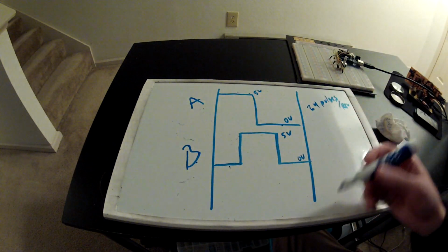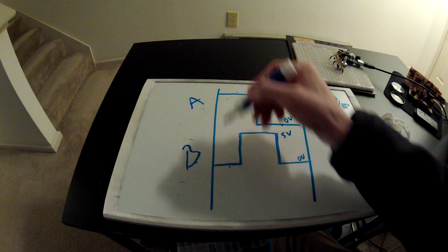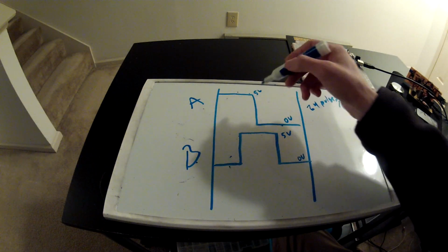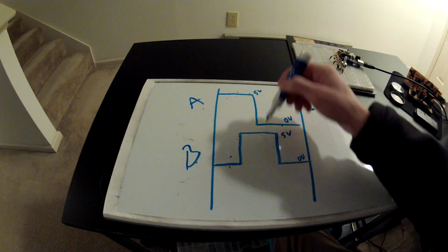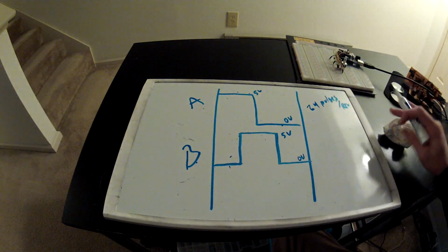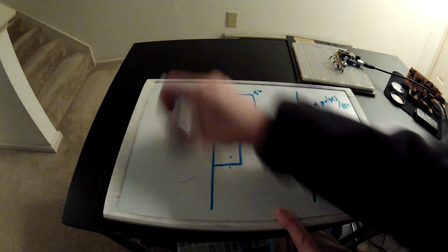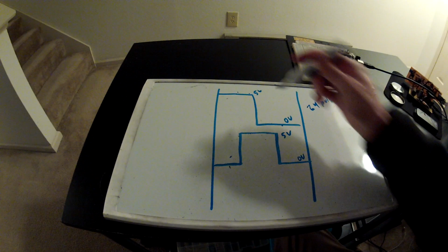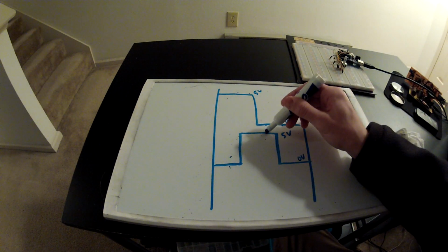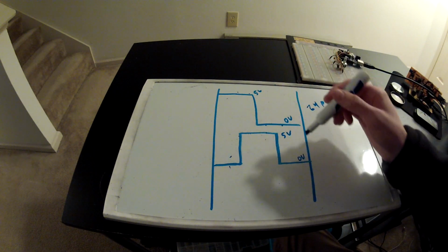And some people call this gray code, where you have a 1 0, then 1 1, 1 0. You just go through it as different states. But I prefer to do it just on these events. My A signal falls. Is my B state high? Yes, that means we're moving forward.